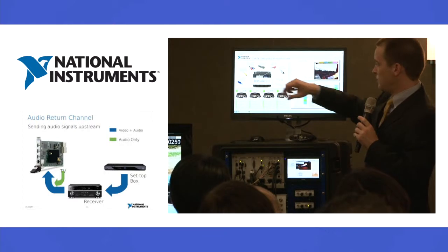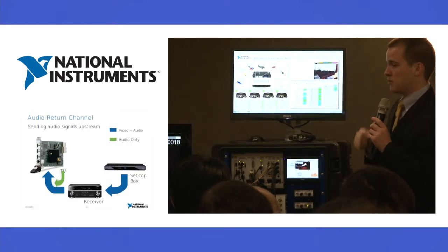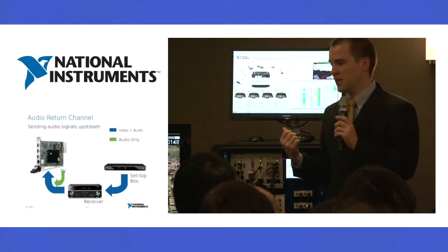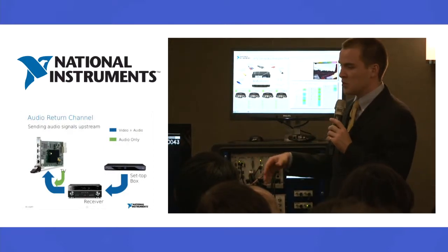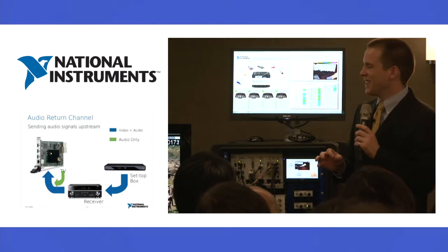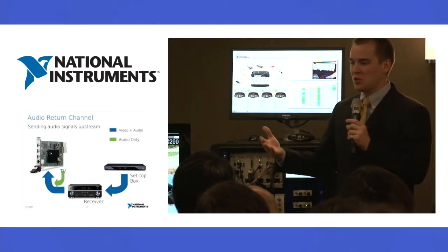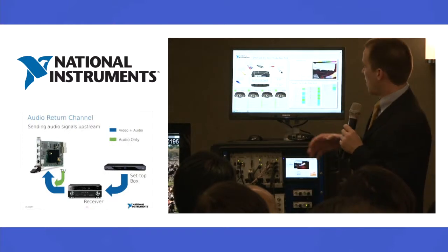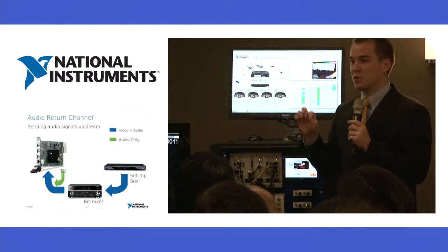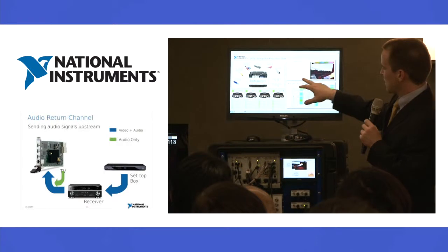On the analog audio and optical SPDIF, on this particular signal, we have a single one kilohertz tone playing. I'd unmute this and let you hear it, but it's a very annoying tone. And you're able to do a quick analysis to make sure those audio channels are working. So on analog audio and optical SPDIF, we're doing the same tests, and you can see the audio spectrum here.